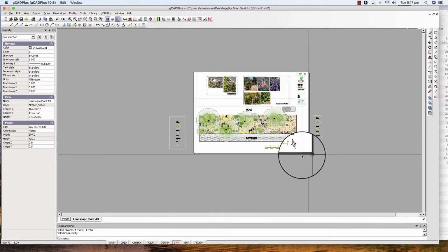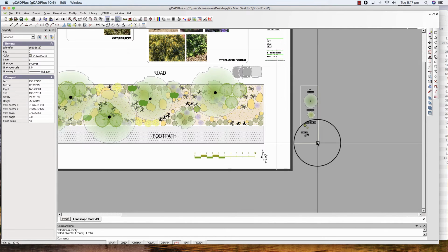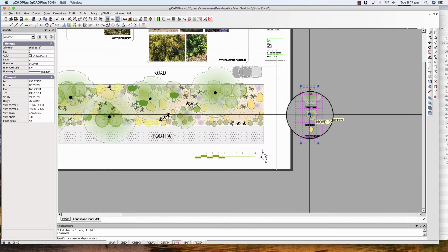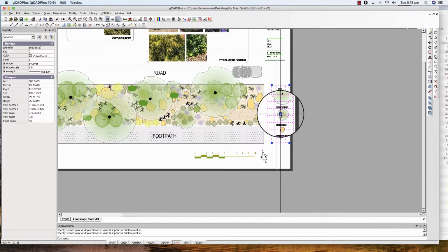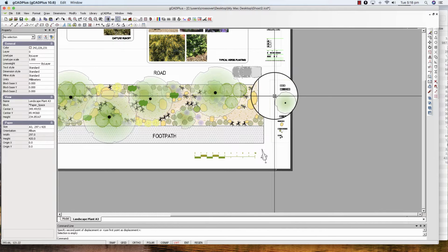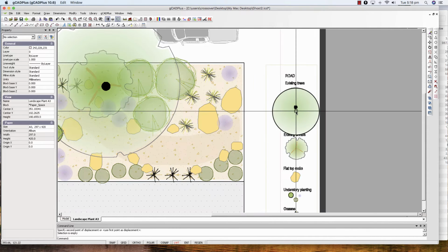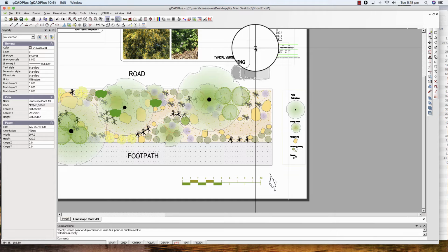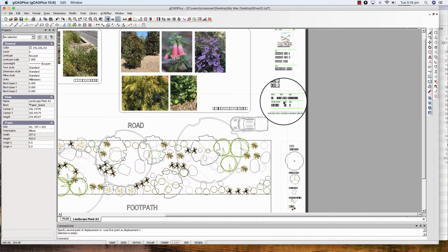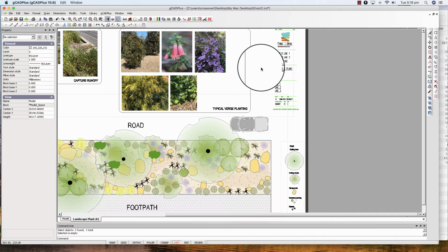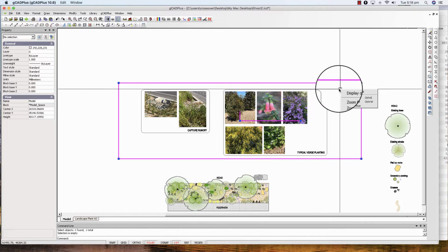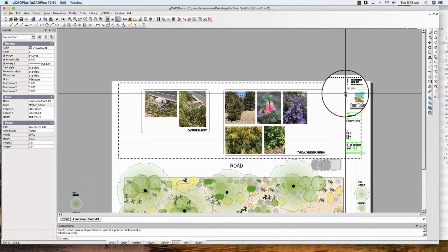What I've done over here is put it a much smaller floating viewport. So I'll take it now and right click and move and put it into position alongside the design. So you may just be able to see these various viewports overlap, but they do enable us to place things nice and easily. So if I double click, I have to be a bit careful. If I move up to the top and double click in here, we should get the magenta box now covering the images, and I'll right click and display it on the layout.